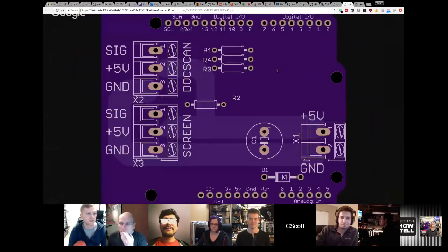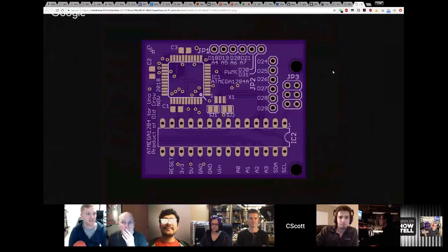Driving those pixels was interesting because the customer had a little Arduino program that ran everything, and the problem was they program like they have a gigabyte of space, and they don't understand that this is an AVR. It's got scant memory, and since they have this JavaScript packet handler and then 540 LEDs going, it just wasn't going to work. So I had to recode everything to use much less memory, and I decided, well, let's just cram a 1284 in there because it will have more resources, and I got everything to work.